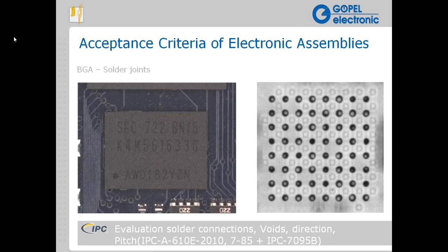Solder ball issues come in a number of different forms. Here's a case where there's really no solder contact at all. You can see the ball sitting on paste. Other cases where there's just a very poor solder joint, partially soldered. In this image you can see that there's some solder flow there, but it's really just kind of sitting on paste. It's not completely soldered. And then of course the head and pillow case, which many of you have probably encountered or at least heard of. And then of course a nice healthy solder joint.